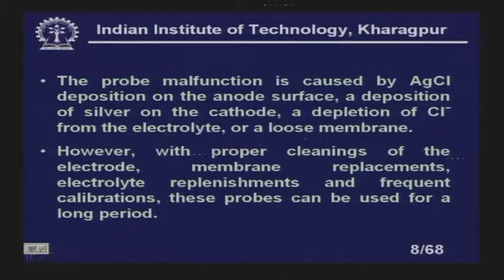This is very obvious for any sensors we use; you need frequent calibrations. Any probe, whether it is measuring pH, conductivity or dissolved oxygen concentration, will have this type of deposition.